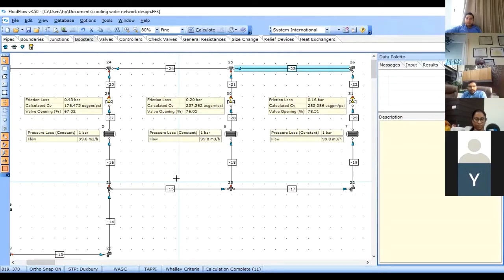In the project we had done for Bharat Oman Refinery, they didn't have any globe valve for throttling purpose. They had the gate valve for isolation. The gate valves are not fit for throttling. So that's why they could not maintain. They wanted to reduce or increase the flow, but it was not really happening. Okay.